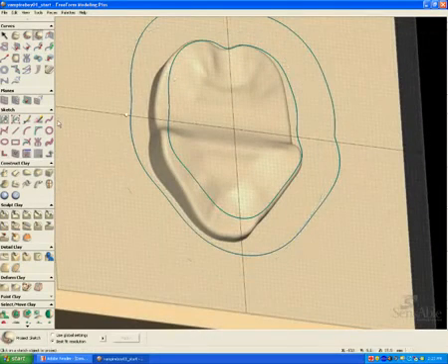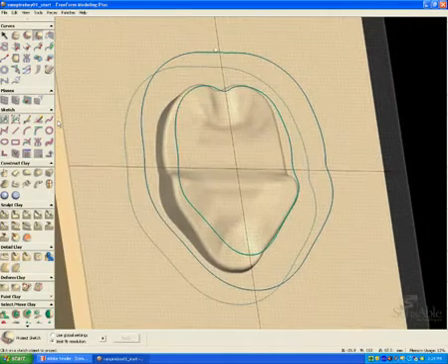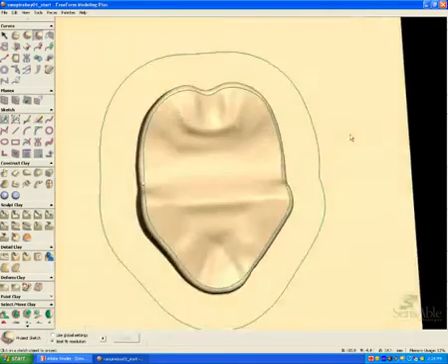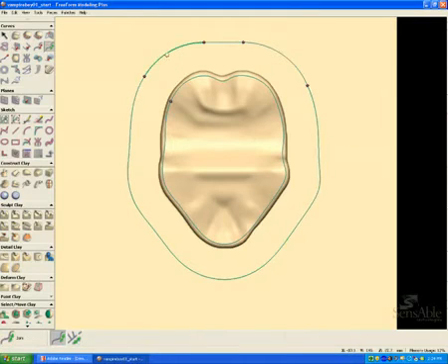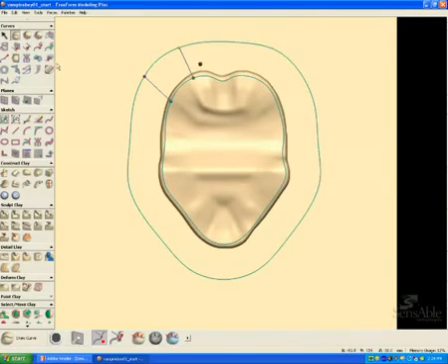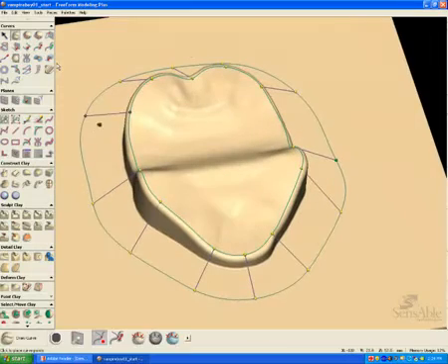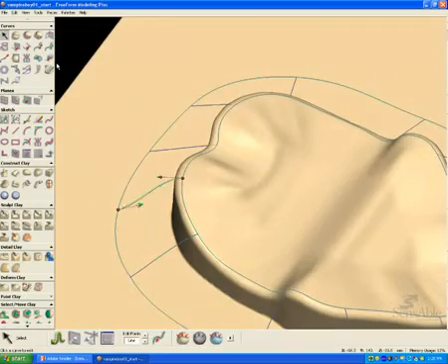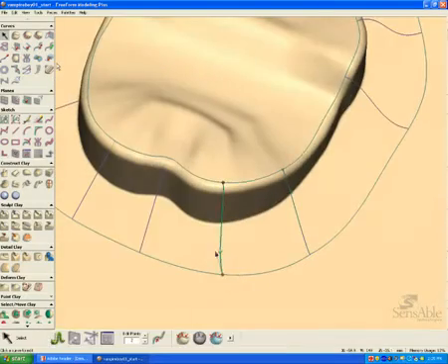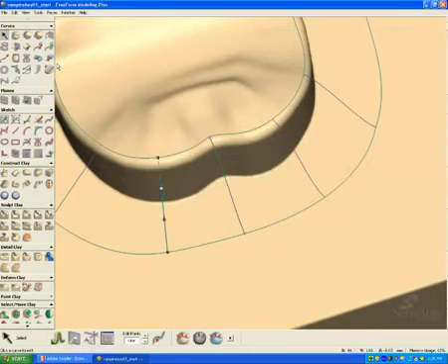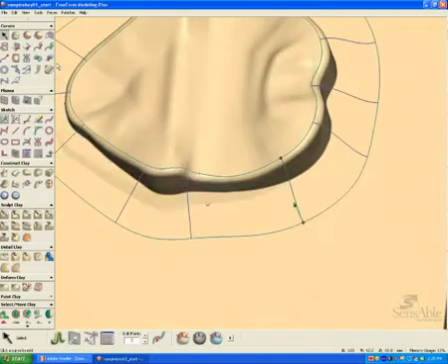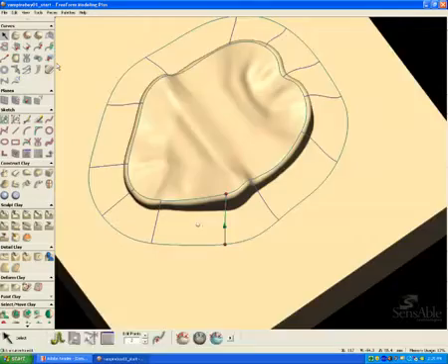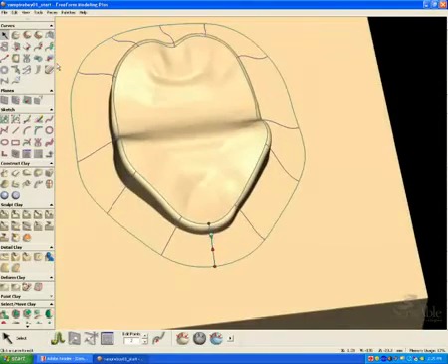Now I want to project these sketches onto the clay and make them into three-dimensional curves. So I'll get rid of the sketch plane, and now I have my two curves, just joining a few pieces of the curve, so it's one curve for each piece. And now I'm going to draw some more curve networks that connect the two different curves, and I'm going to make them tangent to both pieces of the clay, so that when I start shaping these pieces with clay, the transitions between the top and the bottom will be nice and smooth. So you can see those little red discs come up.